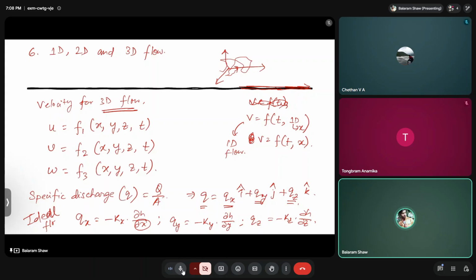Okay, so groundwater, we know how it moves. What is the basic principle? The basic principle is that movement will be from high head, or let's say high potential, to low head, right? So high potential to low potential, right? So now if we know where the water is flowing at what depth, then we can also create contour lines on the water table, right?